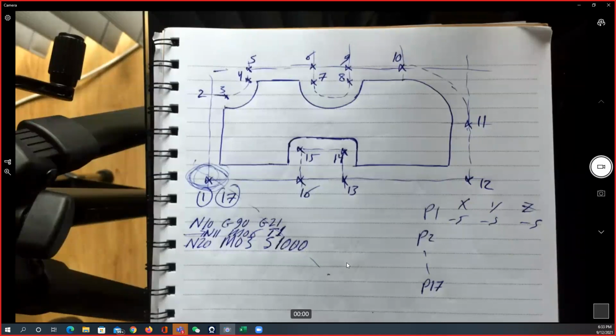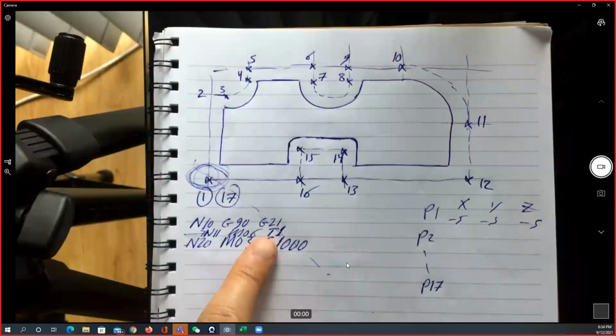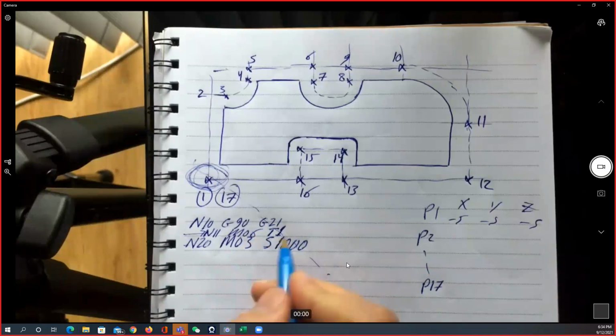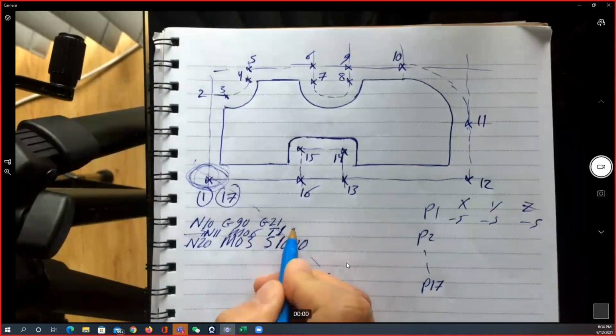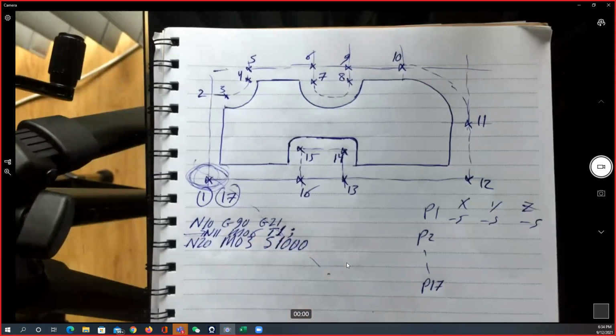So I'll say that the position number 1 is going to carry the cutting tool with the diameter of 10 millimeters. So tool number 1 has been identified here as the 10 millimeter diameter cutting tool. I don't have to mention that here, but just for example, if I'm going to send this code to a friend, I can write down here a comment, like what we do in G coding.